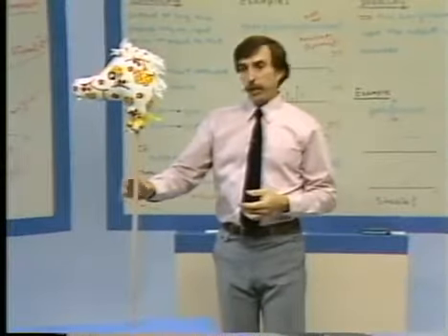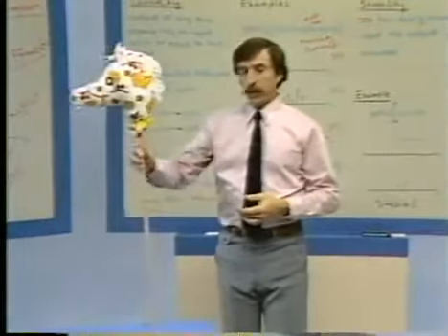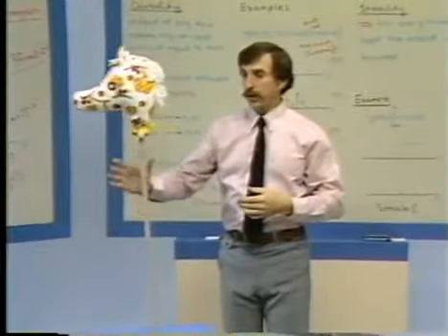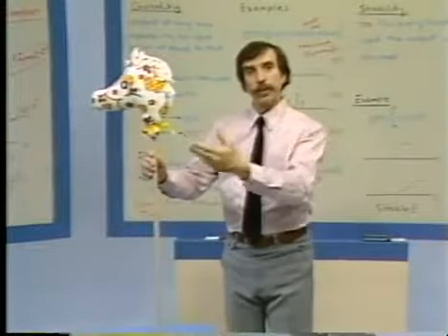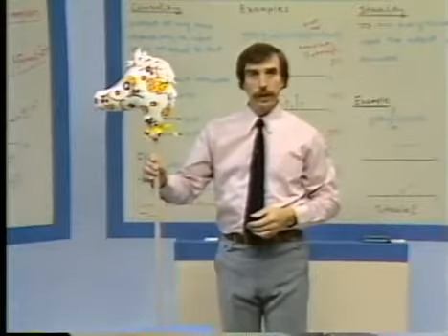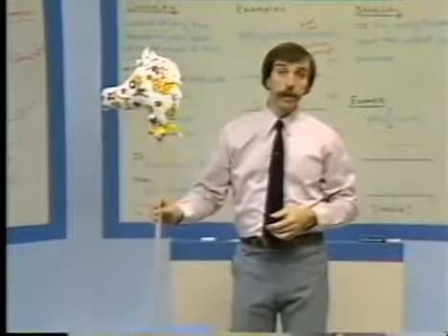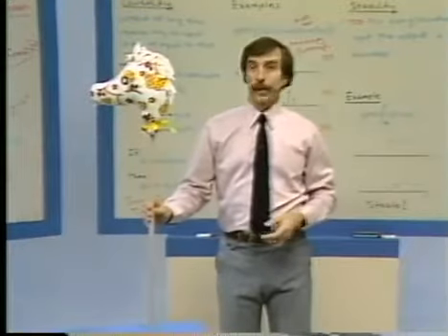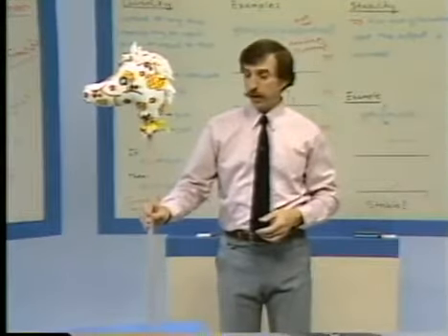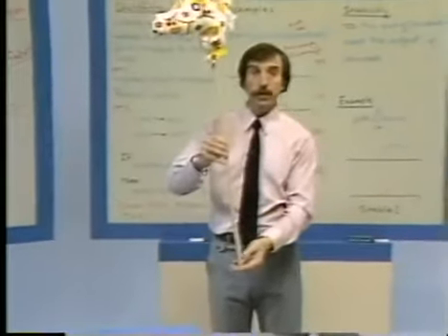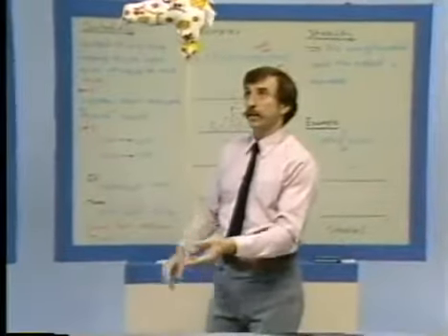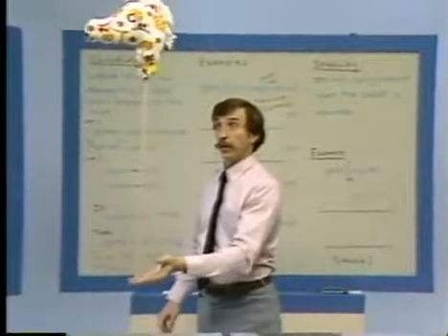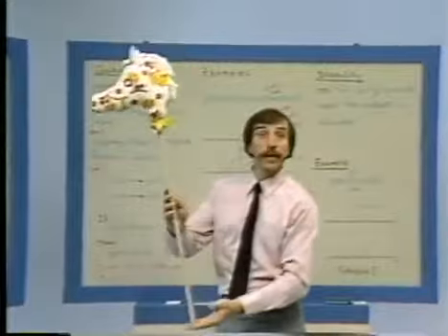although we could conceivably get this to balance, just a slight displacement, because of the fact that the pendulum is inverted, and the output becomes unbounded. Now, an interesting thing with the inverted pendulum, by the way, which I'm sure all of you, if you were anything like me, were intrigued with as a kid, was the notion that you could take an inverted pendulum and, in effect, turn it back into a stable system by using what I'm doing right now, which is feedback.